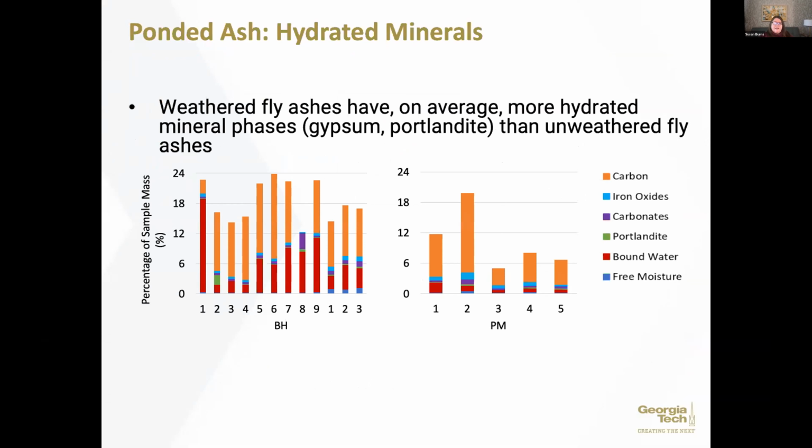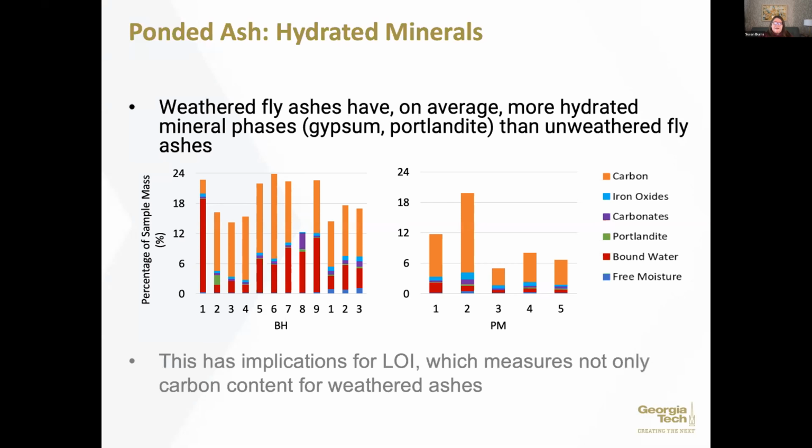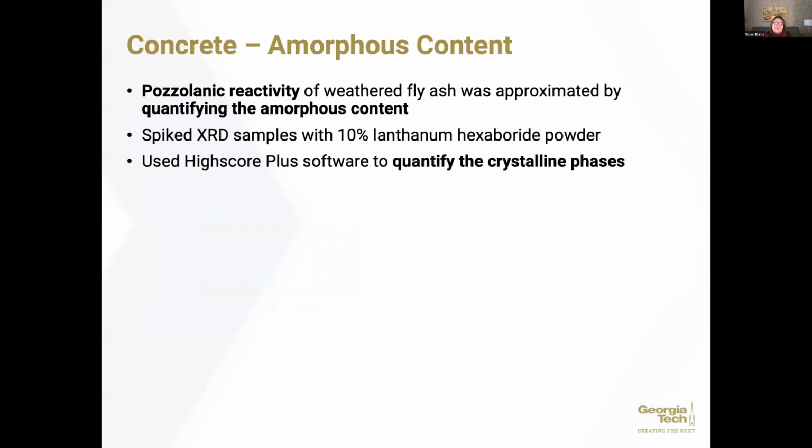In general, the take-home message here is that weathered fly ashes are going to have lots of hydrated mineral phases, gypsum, portlandite, in comparison to unweathered fly ashes. And that means that their LOIs are not necessarily an issue. It's just increased presence of these other mineral phases. Okay, so we don't think LOI is directly corresponding to carbon content.